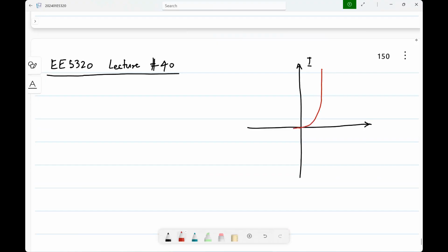By the way, in the reverse direction also, there is something called breakdown, which is also sharp. So even this could potentially be used as a constant voltage source, and it is used. It's called a Zener diode. Only thing is that voltage, first of all, is too large for most of our IC work. And on an IC, it may not be desirable to have junctions breaking down either. So it's not used very often. But the other one is, we looked at this.